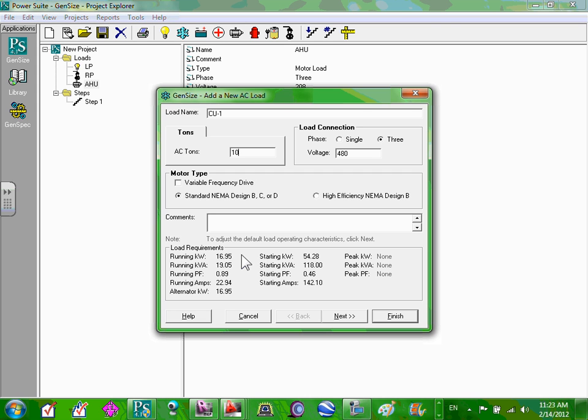Now, actually, if you don't have a cut sheet, you know what I do, guys? You keep putting numbers here until you get the kVA that you're looking for. You can change this number. If I want this one 20, let's just say 15. If I put 15 here, I'm down at 28, right? Maybe I'll move this one to 13.